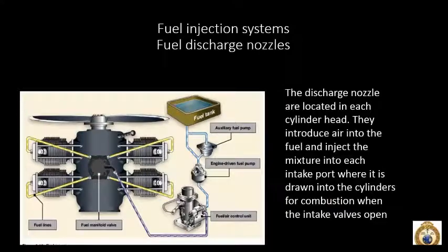Alright, so the throttle and the mixture both play a part in getting fuel into the engine. The mixture kind of changes the quality or the density of that fuel air mixture. As you increase in altitude, you want a lower fuel air mixture, or reduce the rate of fuel going in there for air. Diminishment, I don't even know if that's a word, but we'll work with that for right now.